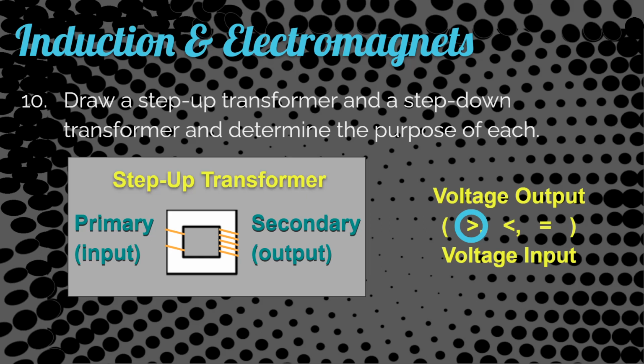You would use a step-up transformer if you were traveling abroad. Really more so if they traveled here. Somebody from the UK comes here, their voltage that they have running through their homes over there is like 220 volts, and ours is 120. So if they plugged their hairdryer in here, assuming they had an adapter for the plug shape, they would also need a transformer so that they could step up the voltage to what is required by that device.